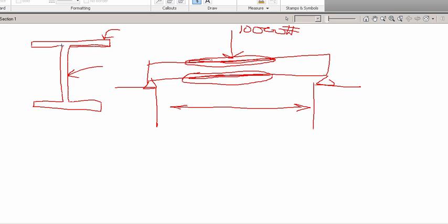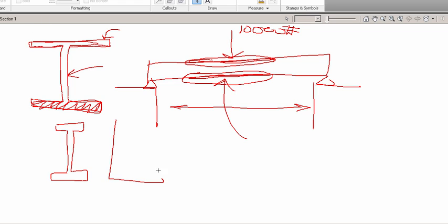So we get more material up here to resist the bending stress, that's what that was referred to, or flexural stress. So by adding in material here versus a narrow beam, a normal flange beam, we can handle more stress with not a lot of extra weight. So that's different than just adding a big old chunk of material, like a big old piece of wood.